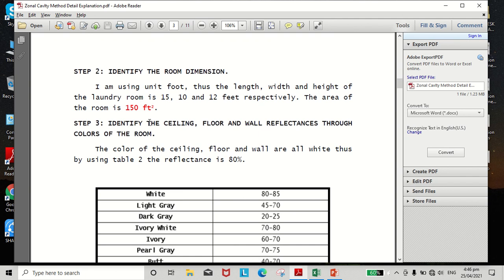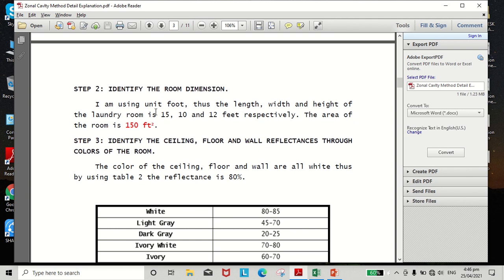In the newer edition of the PEC, you should use meter squared, because the VA calculation and the tables we need to use are in meter squared, not in feet squared. This was an older example, so the dimensions identified here are in feet squared.